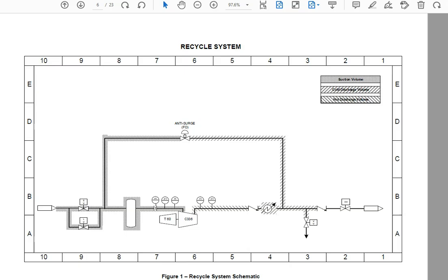So back to the schematic. The turbine is losing power quickly, and we need to do something to get rid of this pressure ratio in a matter of seconds. In this design, we only have an anti-surge valve. It's got to move gas from the discharge to the suction to equalize the pressure around the compressor. We're usually looking at pretty significant discharge volume with a cooler, and it's a lot to ask a single valve to move all those molecules of gas back to suction.